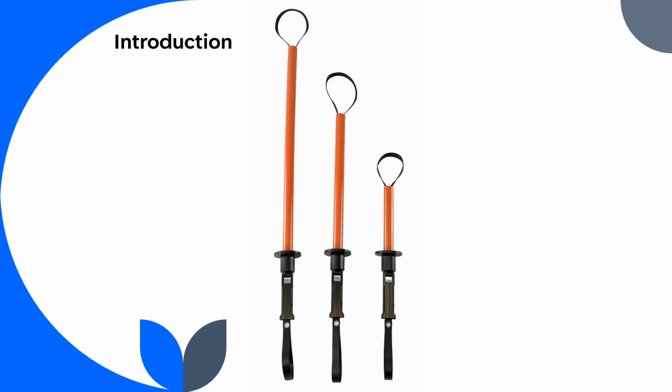You can see the point here. In this area we grab the tool or a cylindrical object or anything we can hold, and in this area we rotate clockwise or anti-clockwise, and it will grab or tighten. So this is one of the extension tools we use in our industries. It's very safe, because this is an extension tool that is not in direct contact with the hammering or line of fire.